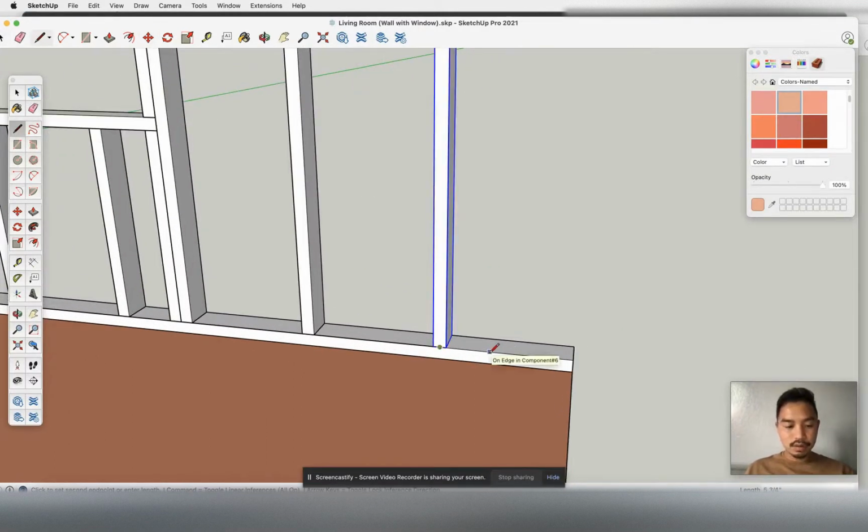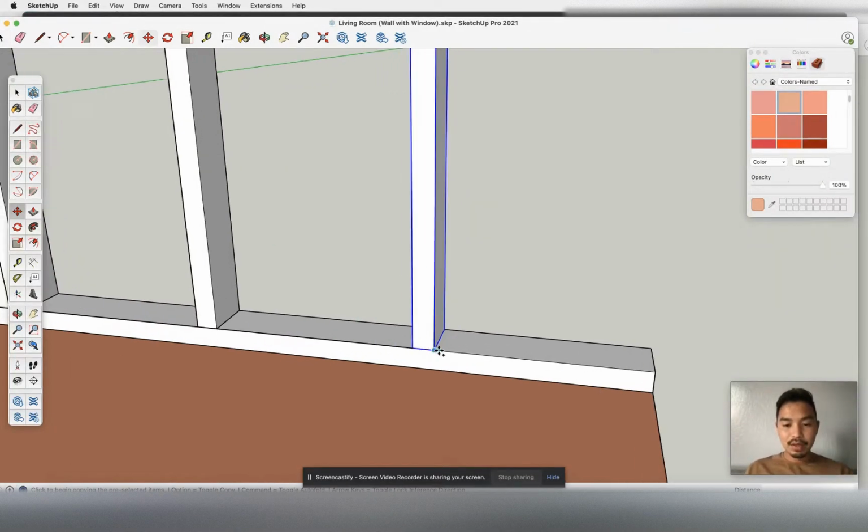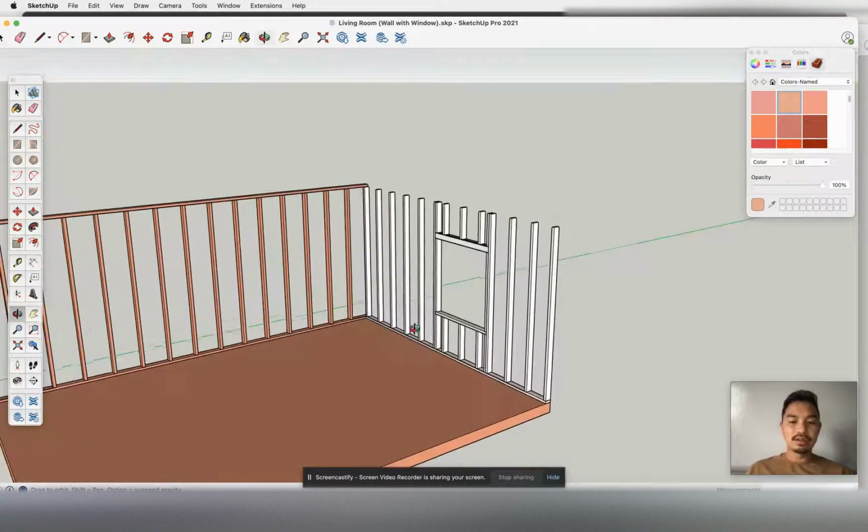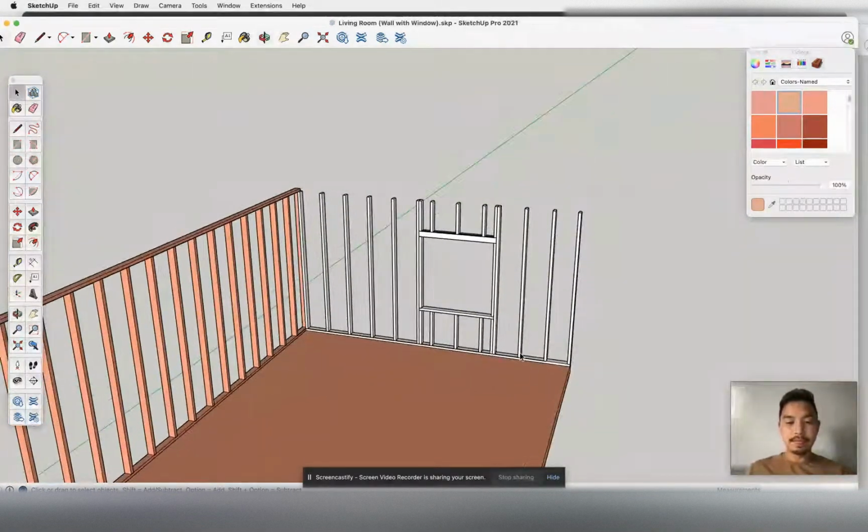All right, let's see how much space we have here. From the center over, we do 16, enter. Oh, look at that. See how it goes past? And that's what you want to consider. If it's shorter than the 16 inches, all we need to do is take this object and copy it to the edge. And that's what we're going to do. M for move, option to make copy. Grab it to the edge and move it to the edge. And now we have ourselves our wall with a window.